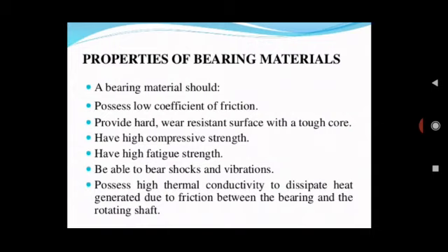Also, the bearing is subjected to different kinds of load on the shaft. These include compressive stresses as well as fatigue loading. Fatigue load is the dynamic load or fluctuating load that acts on the shaft. So such load is also supported by bearings. So we require such a material for bearing which is having enough capability to bear such kinds of load, that is fatigue load, compressive stresses, and it should be able to resist or absorb, we can say absorb.